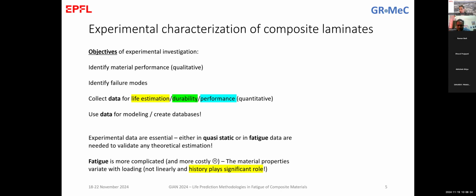So you can increase the temperature, because we know that temperature is significant for composites. You remember the discussion that we had last time about the glass transition temperature. If you have stiffness and you have temperature, we know that composites perform somehow like this. Stiffness drops a lot around a temperature which is called the glass transition temperature, the TG. And it's not only stiffness, it's all the properties. And this region of temperature, we call it the glass transition region. So this means that if your material is loaded at these temperatures, it has a stiffness which is much, much lower than the stiffness that it has at ambient temperatures.